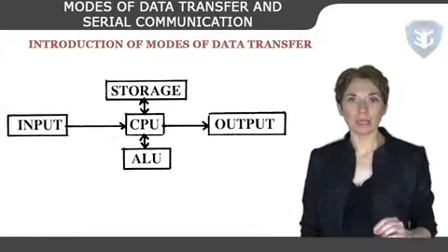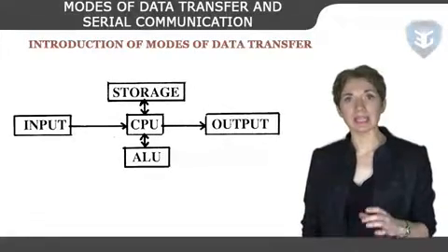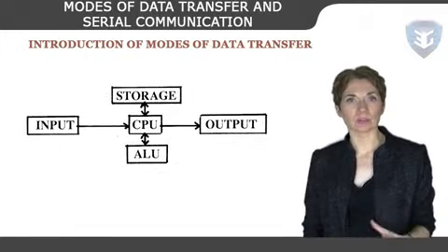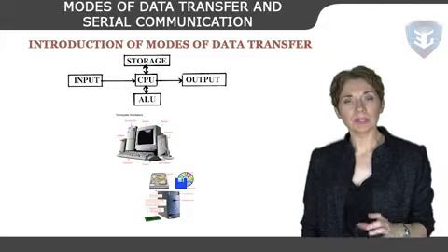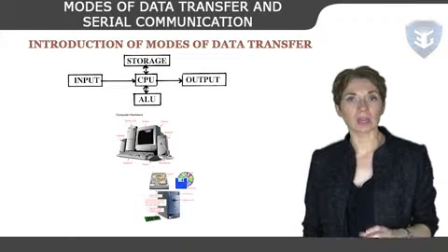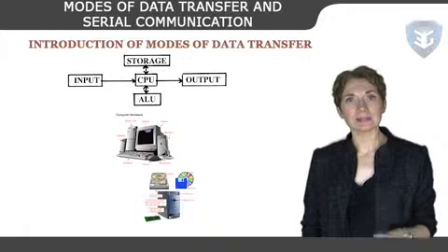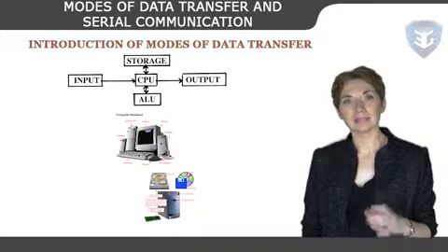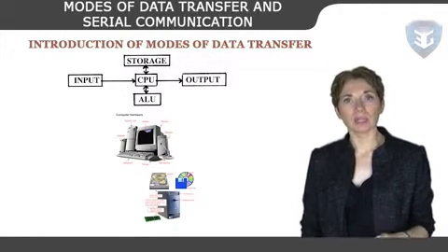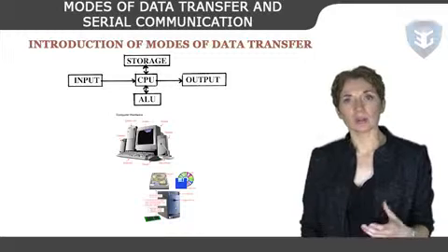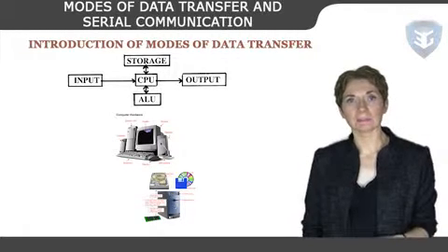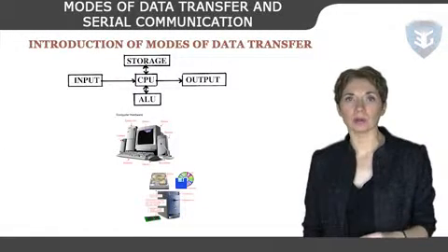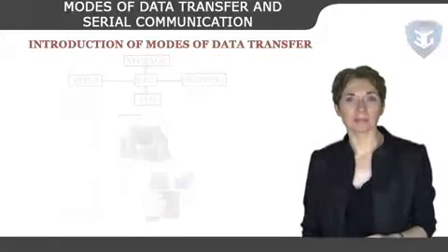Programmed I/O, or PIO, refers to data transfers initiated by a CPU under driver software control to access registers or memory on a device. The CPU issues a command, then waits for I/O operations to be complete. As the CPU is faster than the I/O module, the problem with programmed I/O is that the CPU has to wait a long time for the I/O module of concern to be ready for either reception or transmission of data. The CPU, while waiting, must repeatedly check the status of the I/O module, and this process is known as polling.